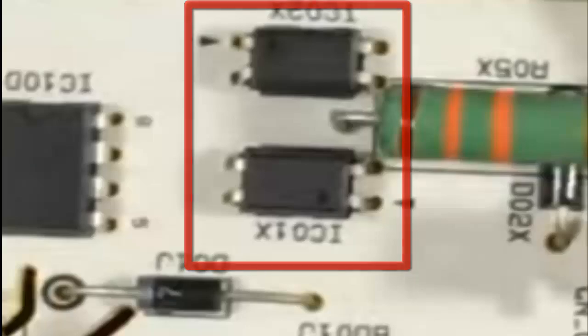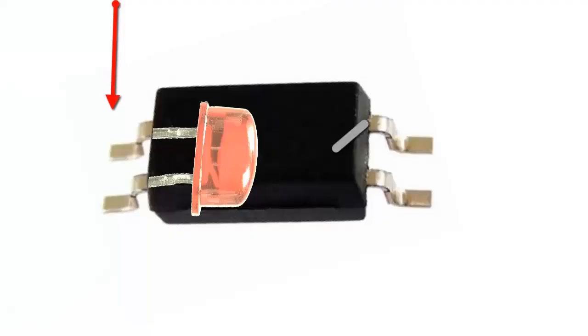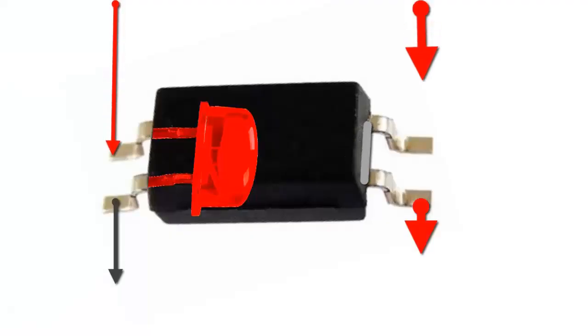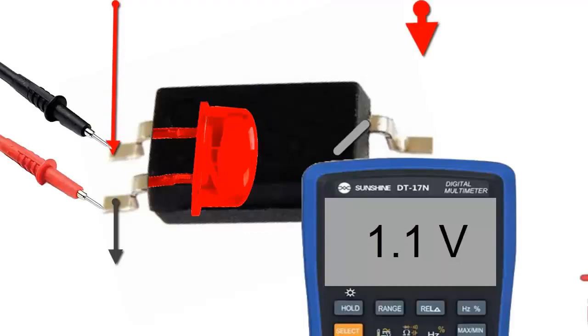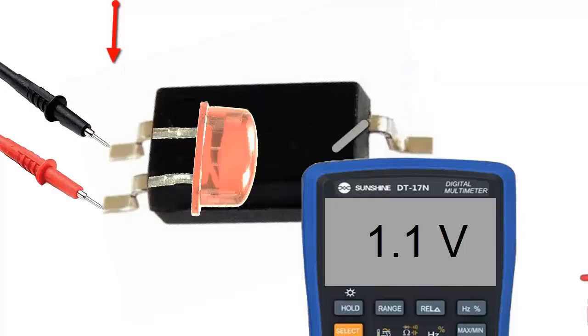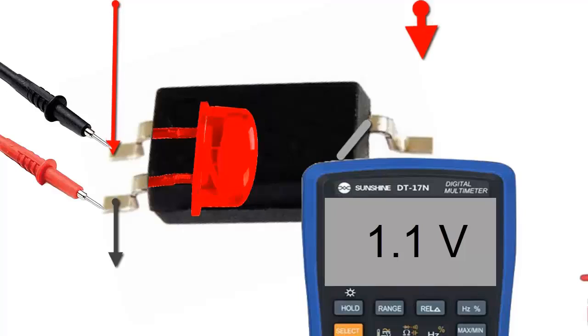Now let's look at the procedure for testing an optocoupler. A key aspect of understanding how to test these components in the circuit is to understand the voltage drop across an LED. Unlike a normal diode, which has a drop of approximately 0.7 volts, an LED has a drop of around 1.1 volts, although this may vary slightly depending on the manufacturer and device specifications.